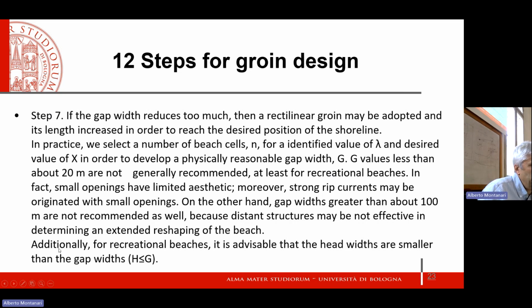And another thing, with recreational beaches, it is advisable that the distance between groins is larger than, if you adopt T-shaped groins, the width of the T. So if you have gaps between the groins that are smaller than the width of the T, again, you feel like in a prison, you know, or in a closed pool.